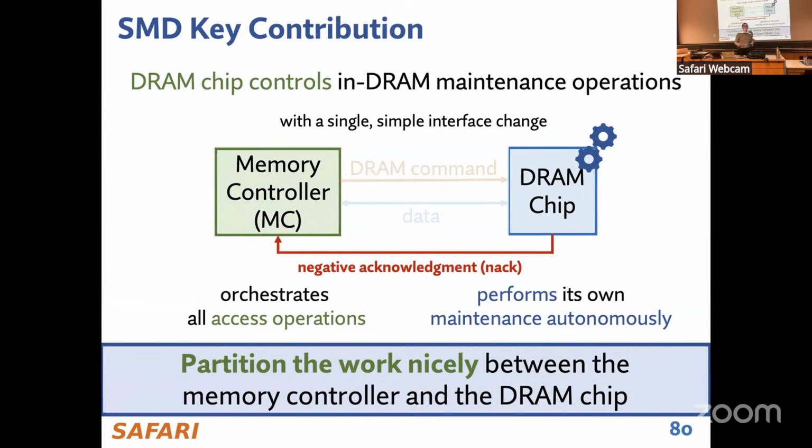That way, they can actually design their mitigation mechanisms internally. They can do a retention-aware refresh, etc. They can implement many, many ideas much more easily. So the way it was done in the DDR5 standard is a little bit bad. It's not like what we proposed, actually. It was essentially, you cannot access the DRAM chip while that's going on, right? This alert backoff.